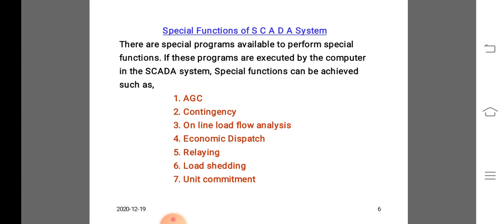Status indicators include alarm signals, over temperature, low relay battery voltages, illegal entry, and whether switches and circuit breakers are open or closed. Such information is provided to the ECC through a periodic scan of all RTUs. A second scan cycle is typical.